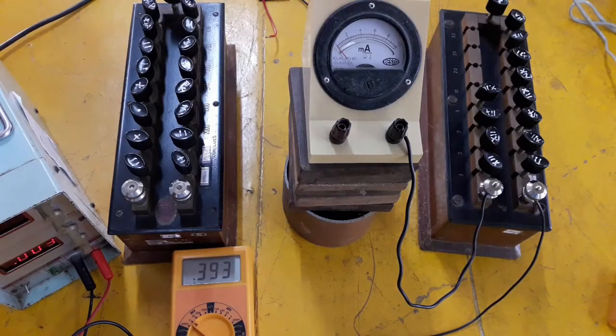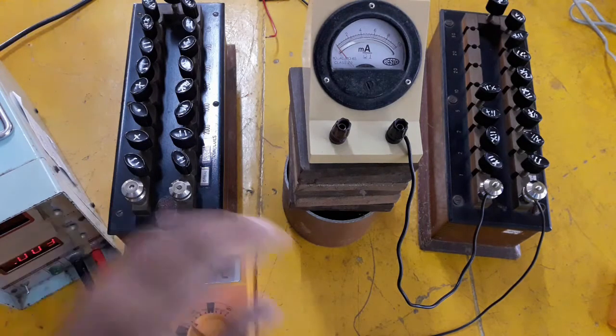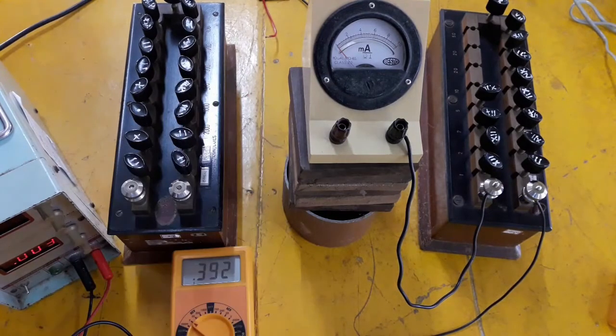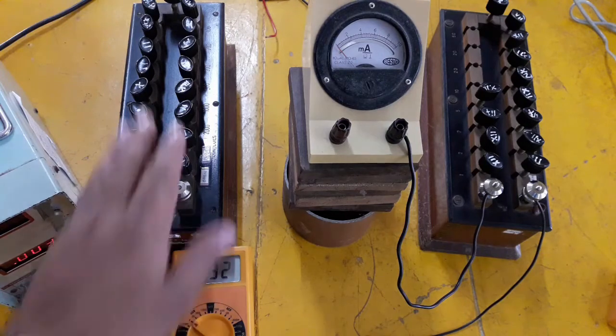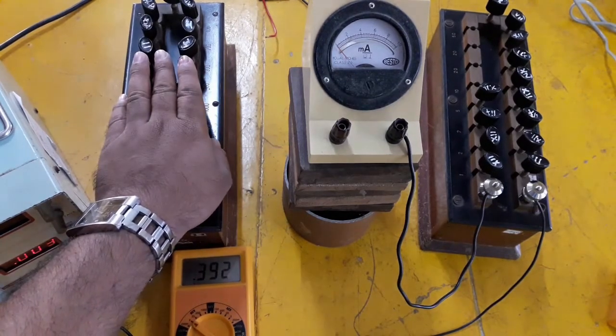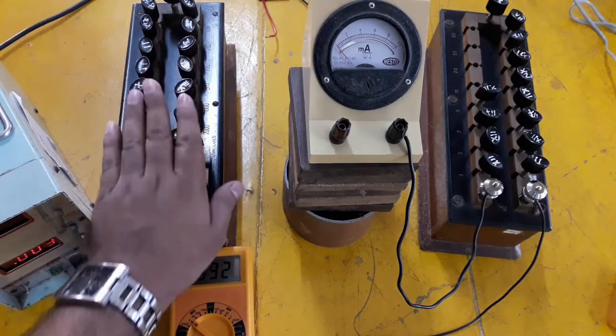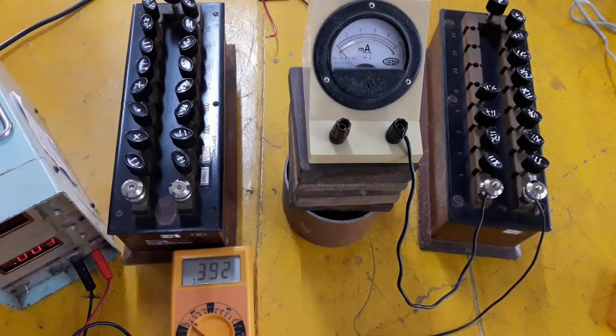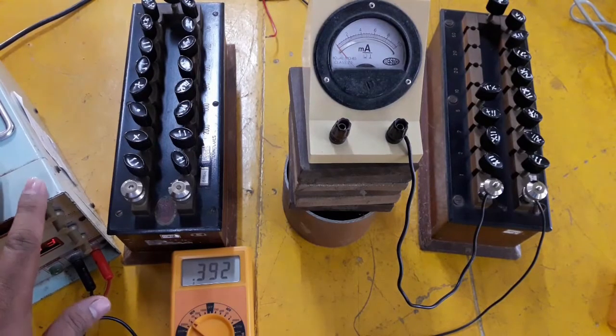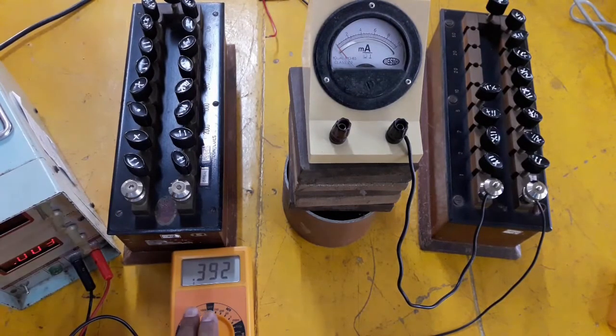Alright students, so now we are ready to do the second part of this experiment, where we are going to replace that circuit with an equivalent circuit. As you remember, while explaining to you, I told you the RTH comes out to be 75 ohms. So this is going to be the RTH, which is going to be 75 ohms, and we calculated the Thevenin's voltage to be around 0.393. So this is the power voltage supply that I have, and we can see in the multimeter it's adjusted to 0.392 here. It's fine. Okay, so I could not do that fine adjustment to 0.393, but this is 0.392. Fine. So we are ready to take the reading.